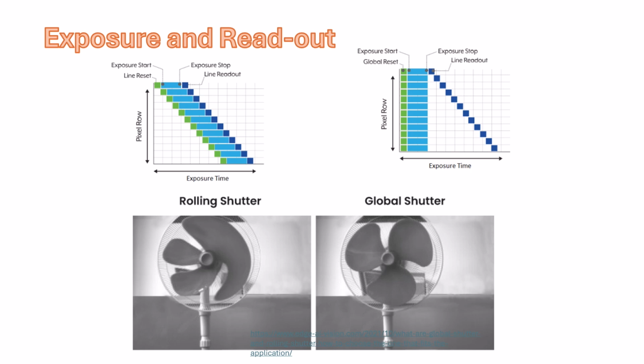And so in episode 66, we talked about different exposure strategies, but the important thing to recognize in this diagram is not the difference between rolling shutter and global shutter. It's that this exposure time, the blue time, is typically set to set the exposure levels where you're not overly saturating the sensor for most of the range, but then the digitized values of the signal are evenly spaced over the range of the well capacity of the pixel.